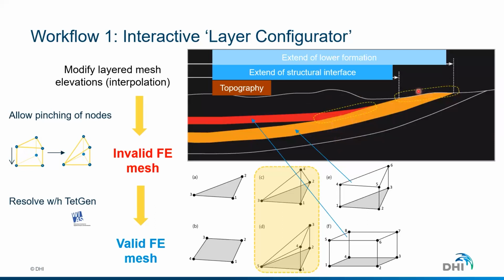You can, for example, have a case where it's outcropping here, and then the topography is fixed. So FEFLOW will know that the slices forming the layer in yellow have to stop in this location. And this brings to a situation where there is a slice intersection, and in this case, FEFLOW offers you a number of possibilities to solve this slice intersection.